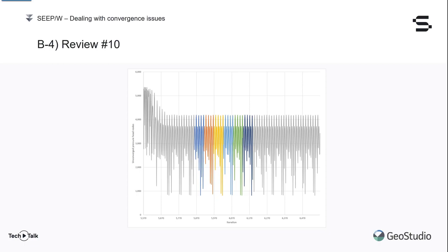the number of iterations climb up. This indicates the solver is stuck in a repeated substitution loop which won't provide any better results even with a large number of iterations being allowed. High nonlinearity in the hydraulic conductivity functions used for the various materials in the domain is causing this convergence issue.